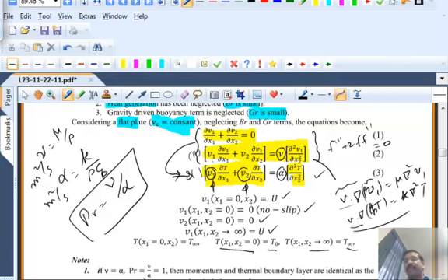So what we are saying is, if you give me a matrix A, and I operate it on X and I get B, it's a linear system of equations, for example. If you have another matrix A times Y equal to also B. Now, if the matrices are the same, same operators, and the forcing term is the same, then the solutions X and Y must be the same. Right? So that's the kind of argument that we are making, that the operator V dot del that operates on rho V1 is the same that also operates on rho Cp T. Okay, so the convective process for momentum is the same as the convective process for energy, and the diffusion process for momentum is the same as the diffusion process for energy.